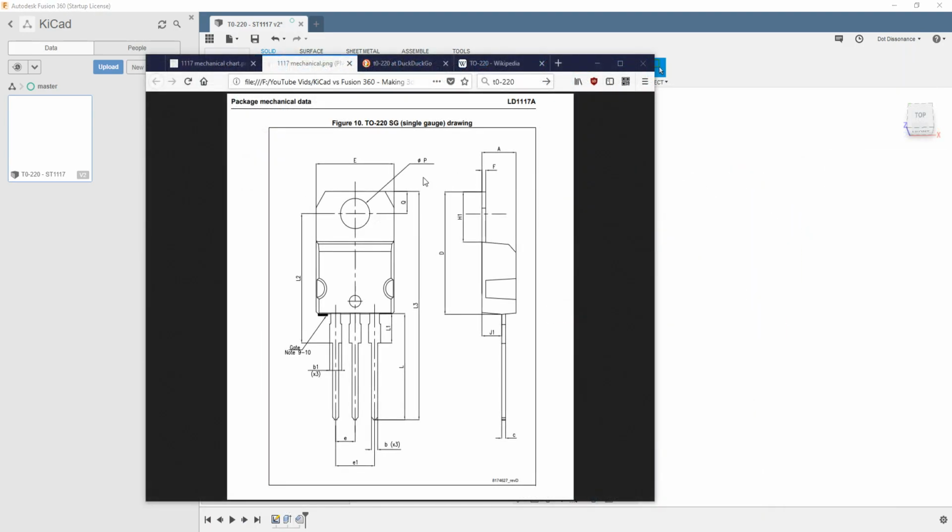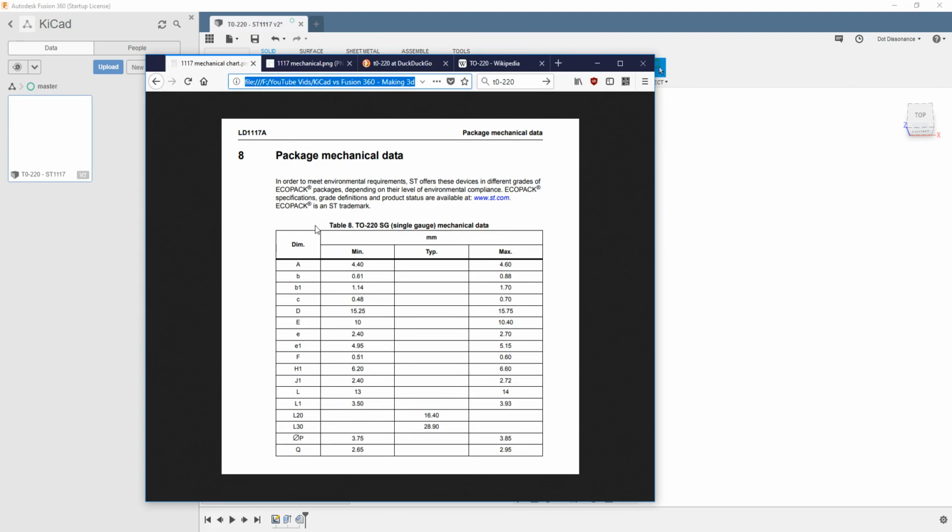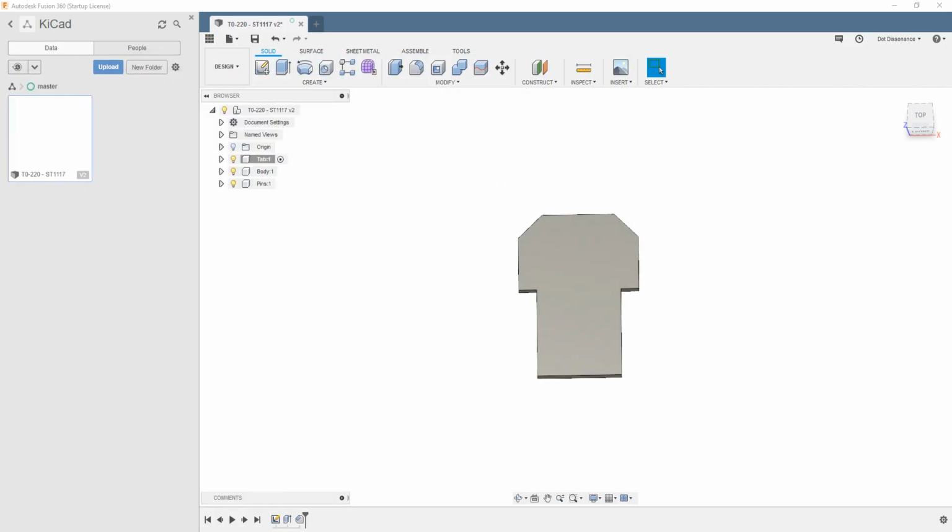So then over here, our hole, we've got a diameter of P, and it is down by Q. So we'll go over here. The diameter is, it's a 4 millimeter hole. It's for an M4 fastener. And Q is, let's say, 2.8. How about that? We'll go with 2.8.